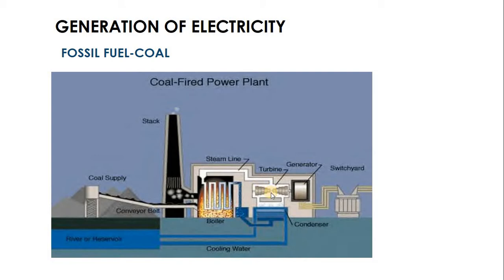And as the steam drives the turbine, the turbine begins to turn, and because the turbine is coupled to the generator, it turns the rotor of the generator to generate electricity. Now, after the steam turns the turbine, it will lose some of its energy, it will lose velocity, it will lose pressure, and it will also lose some of the heat. When that happens, it will come here where we have the condenser.